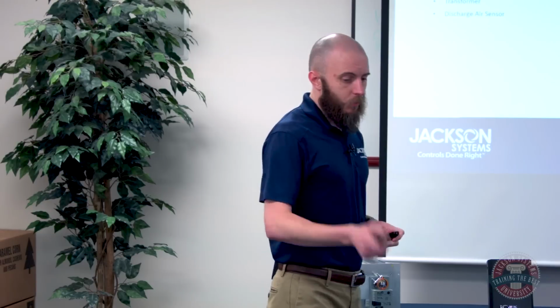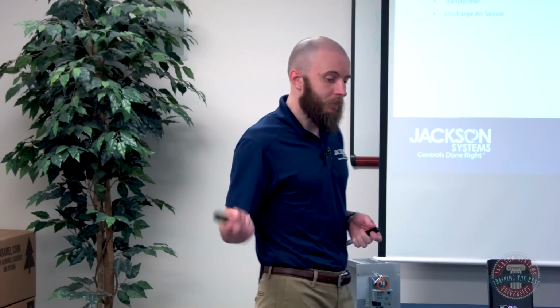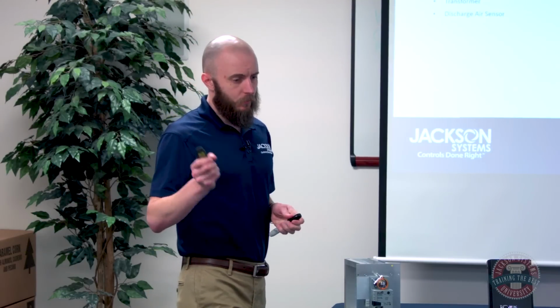And we want to be sure of how much load we're putting on that transformer. With your equipment transformer, you can't really be sure all the time how much load's already on it. So by putting in a separate 40 VA transformer, I know I have 40 VA available for my dampers and my thermostats. I'm good to go, and then you don't have to worry about it again. So that's the last thing I have.